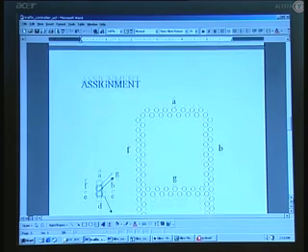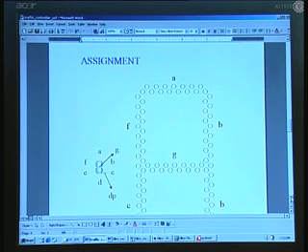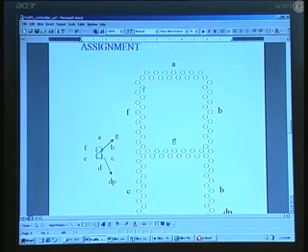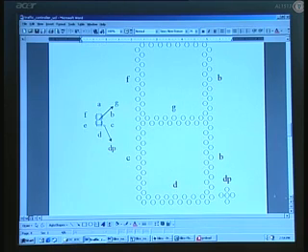Now, of late you would have noticed on the roads there are timers displayed with a big display. Each of the displays is actually comprised of some 15 LEDs or so for each of the segments. For example, this you are already used to. There is a 7-segment display, A through F and G, with a right decimal point, and I have put the same thing over here so that we can form a bigger display. Each of the segments will have some 15 LEDs or so in this placement shown here, and there is also a decimal point here.